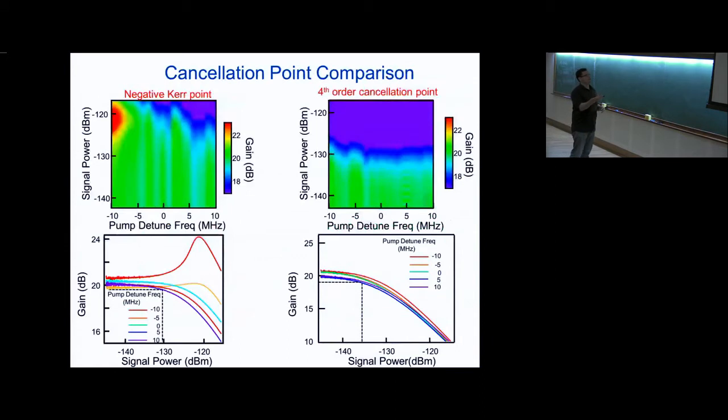Here is the sort of standard graph. This red pimple-looking thing here is this fourth-order detuning shark fin characteristic effect. If we move to the cancellation point, the first news is good. There is none of this shifting. You see this curve is very flat here. And in fact, all the dynamic range curves are very similar, which is what we expect from pump depletion theory. The problem is it didn't actually get better. So this is open challenge number 1.